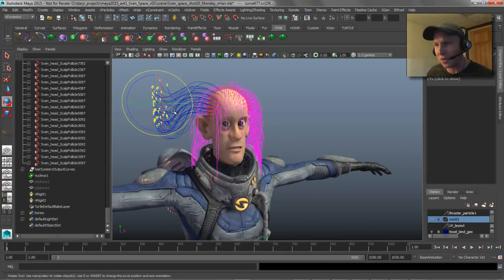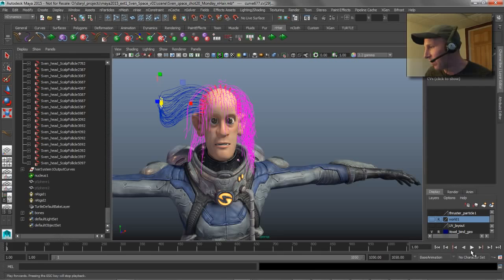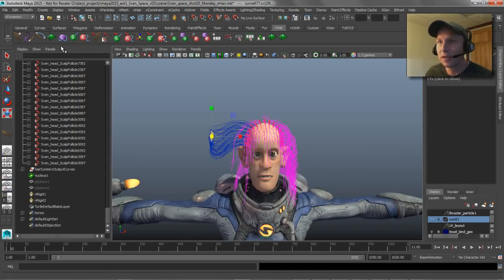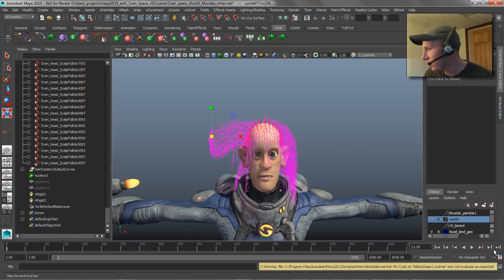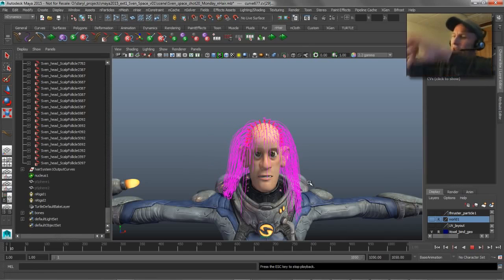You can also jump into your scale tool, right, and hold that L key down and then pull those guys to a point, right? Taper those guys down into a fine little point. So now if we play this back, obviously our start position is this guy. Oops, let's display our current position here. Just click the current button and play that back one more time. So it sort of drops down and relaxes out.